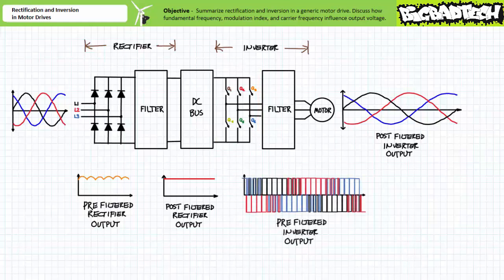The inverter, in summary, can be viewed as a collection of high-speed solid-state switches that selectively connect or disconnect the DC link for various amounts of time and with a given polarity. The result being a type of pulsed output. When the filtration circuit smooths out the pulsed output, we are left with something mimicking three-phase AC, only this time frequency and magnitude are variable. This type of inversion process is known as pulse width modulation, sometimes commonly referred to using its abbreviation, PWM.